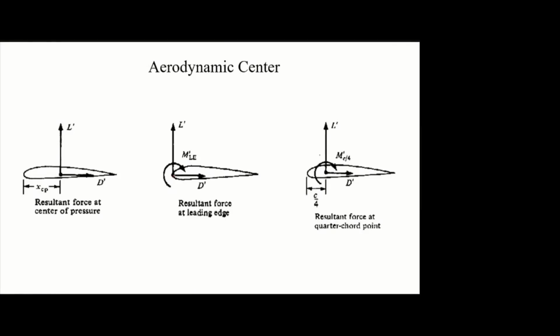So we have taken n number of reference points on the chord line first. We hold the aerofoil at the leading edge point. We are changing the angle and drawing the CL curve and CM curve.